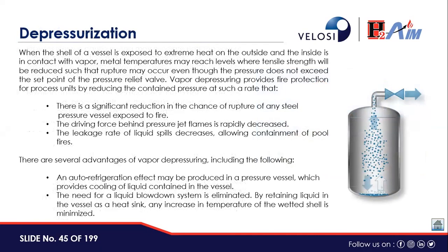Depressurization is the other part which I mentioned. One is isolation, where you isolate incoming fluid by an ESD valve, which is automated, or by manual or motorized valves. Similarly, if you want to relieve the containment of the plant in case of any emergency, there could be a relief to atmosphere, if it is a gas, or through flare or burn pits. From the relief valve point of view, there are PSVs and BDV valves, or vents. So depressurization is also required in case of any emergency.